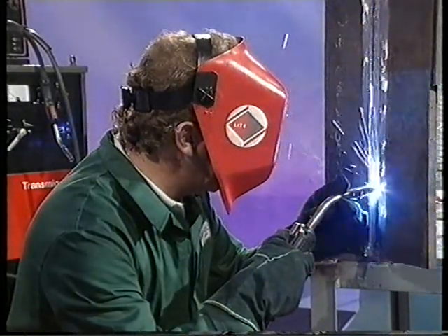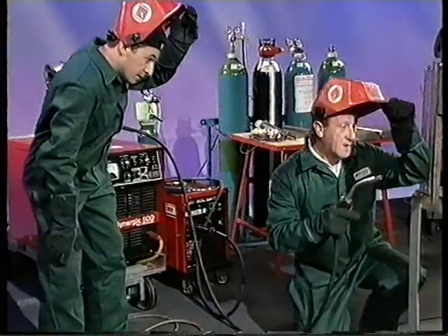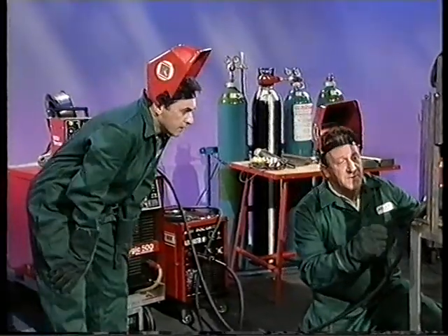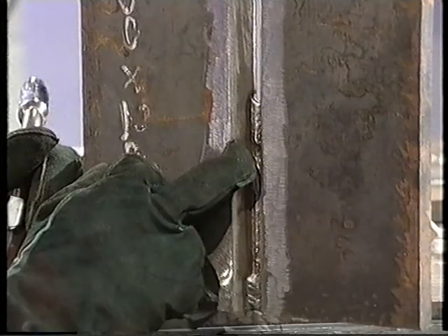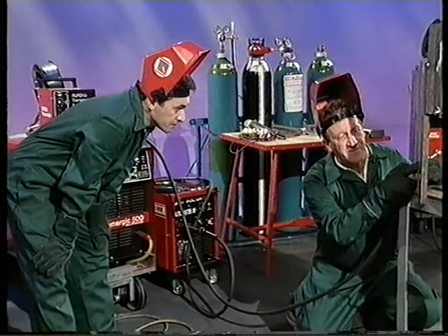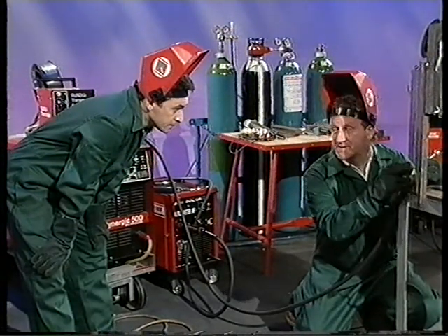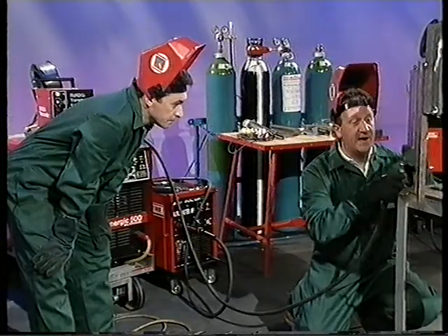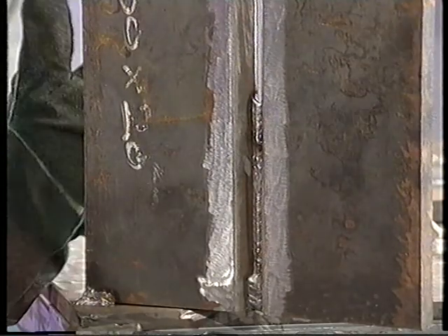Not a harsh dip, that's with plenty of voltage on it. Right, Mel. Okay, so you can see there's the lump that I was talking about. That's no problem, we'll grind it off afterwards, but it's possible there's some lack of fusion in that. But by the time we got it into the crater itself, the weld was running well, and we've achieved good penetration on the back and a reasonable pickup.